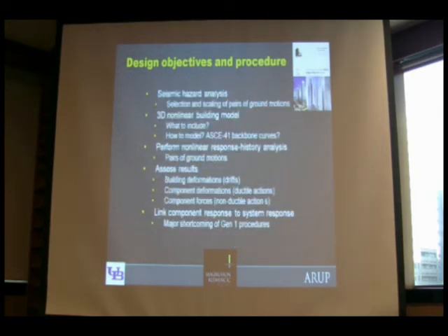We provide procedures for seismic hazard analysis, and we require that the engineer of record undertake a formal seismic hazard assessment, and this is appropriate for a tall or super tall building. We require the development of 3D nonlinear building models for regions of moderate and high seismic hazard, and we provide some counsel on what has to be included in that building model.